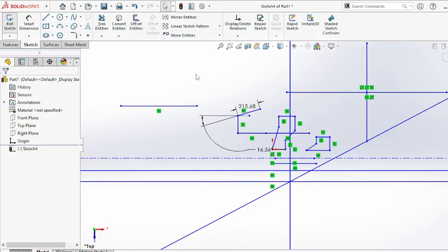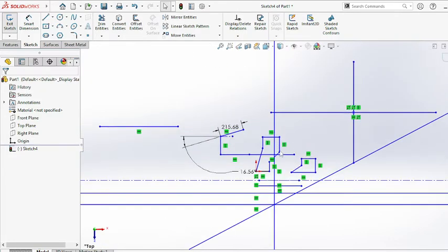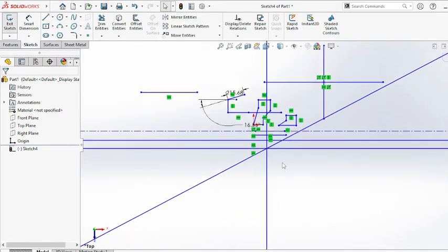See, in AutoCAD, how to zoom in and zoom out the page. Just roll the scroll button back and forward to zoom in and out.